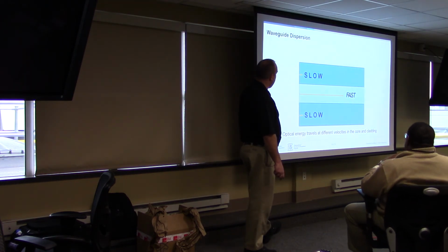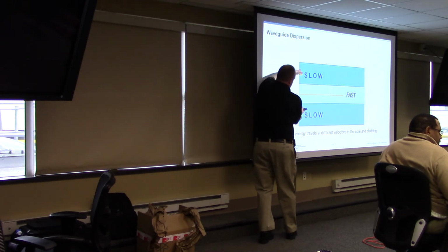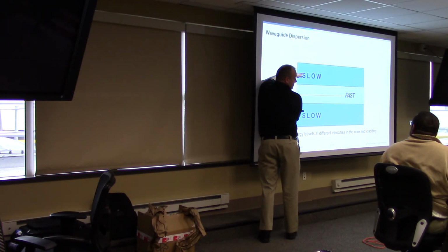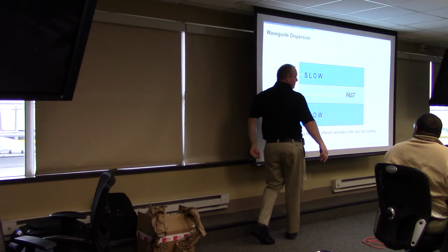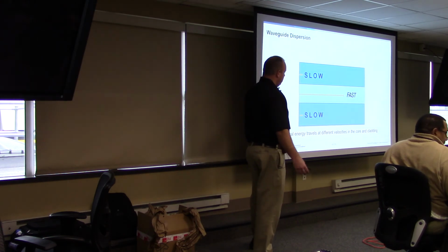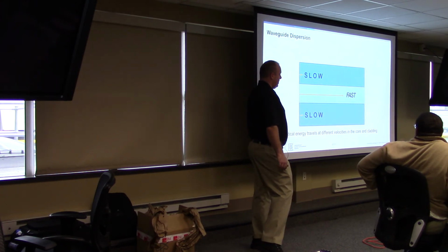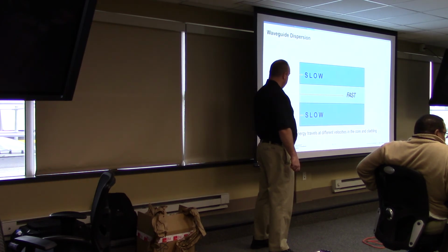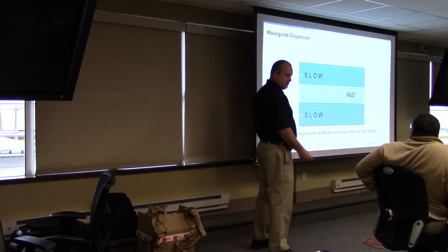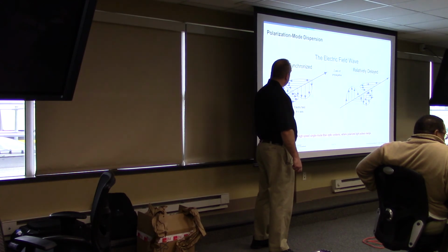This is the waveguide. If for some reason your core is this, and the other core is that, now you're shooting light into the cladding, and you're shooting into the core. Then on the other side, you could get multiple copies of light depending on the connection on the other side. But that's what waveguide is. It travels at 2 different velocities, so you get copies of light. And that's a mating issue, just trying to make sure you have it mated.